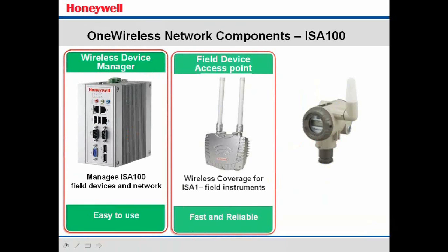The wireless device manager is, like I said, the brains of the operation. It manages the field instruments and the network devices. It's the gateway between the wireless world and the wired world. It's the security manager. It controls everything to do with the wireless side, meaning everybody that's allowed to join, and then obviously who's not allowed to join as well. The interfaces available out of it are Modbus, HART, OPC UA, DA, CDA, and a GCI tunnel.